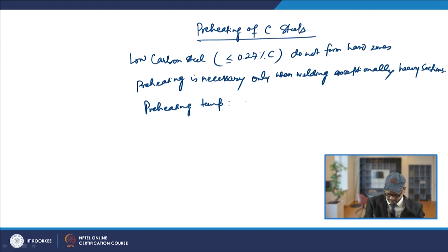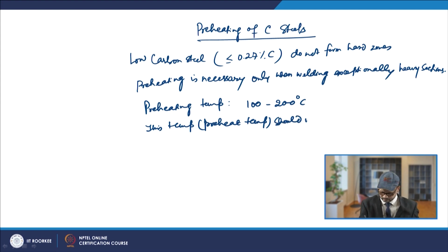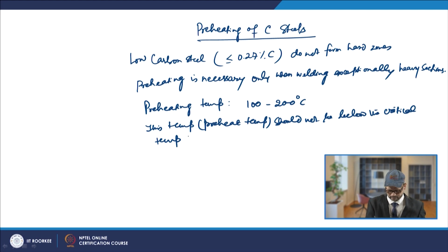But there is another thing: this preheat temperature should not go below the critical temperature for the transition from ductile to brittle behavior.